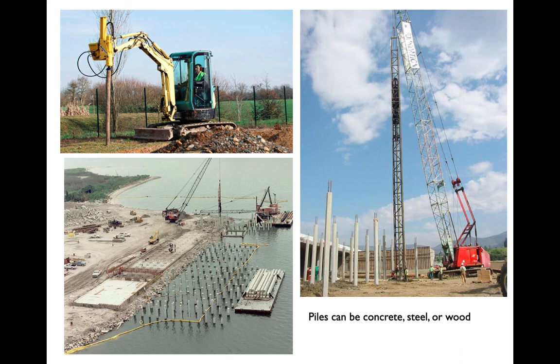This is what a piling operation looks like in a maritime environment. And you can see we've got a pile driver here on a float, and that pile driver is going around jamming these concrete piles into what is probably very poor soil, right? There's going to be a zone of water and then a zone of liquefied soil, and that liquefied soil is what they're going to have to rely on for the friction fit.